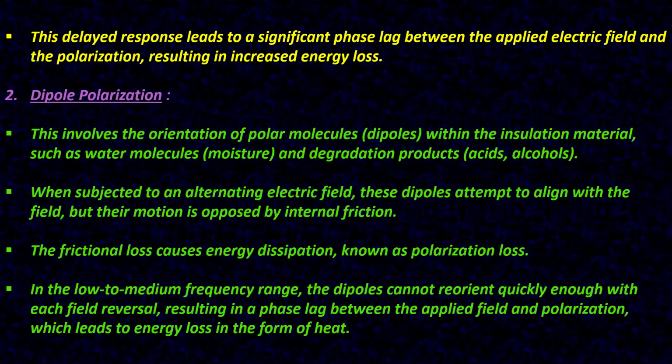The frictional loss causes energy dissipation known as polarization loss. In the low to medium frequency range, the dipoles cannot reorient quickly enough with each field reversal, resulting in a phase lag between the applied field and polarization, which leads to energy loss in the form of heat.